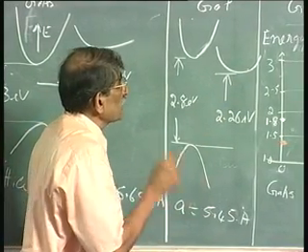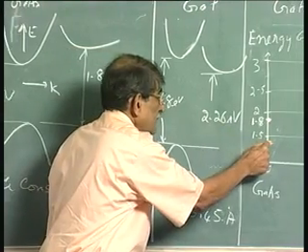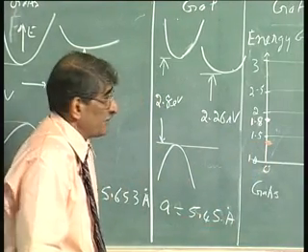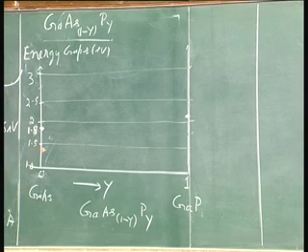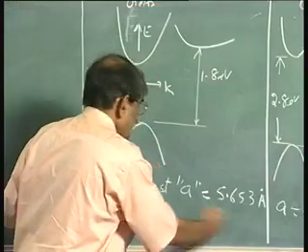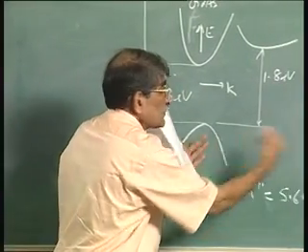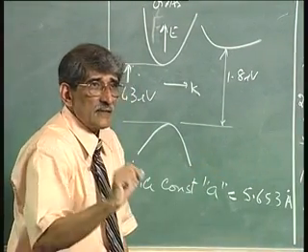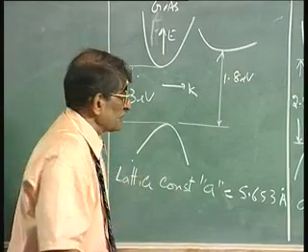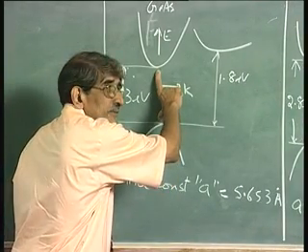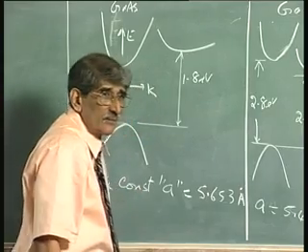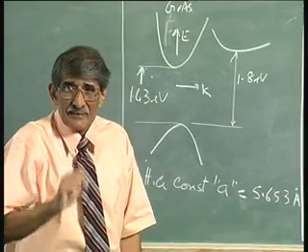So, if I make y equal to 0, the minimum band gap is 1.43. If I take y equal to 1, the minimum band gap is 2.26, the indirect band gap. Now, what happens is when you mix them together, the lattice constants change almost linearly. Without getting down into the physics of that, the direct band gap links with the direct band gap here almost linearly, not exactly linear.